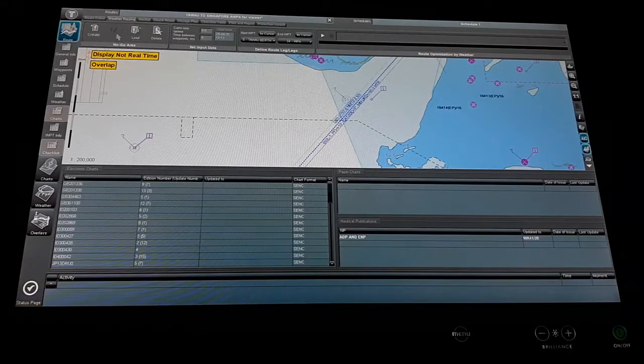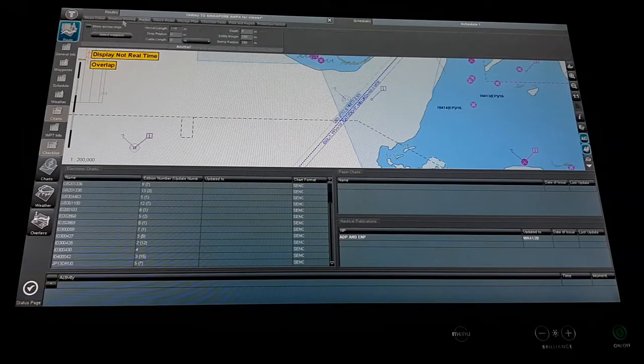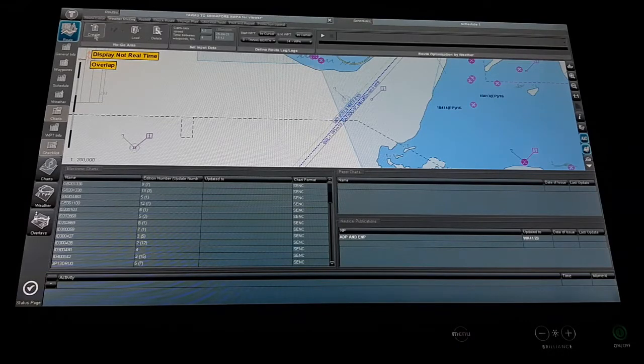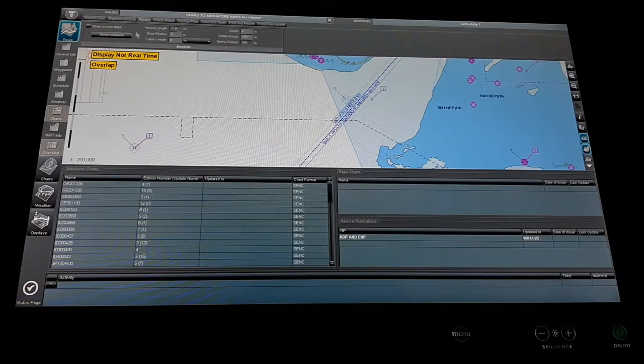After that, we go to weather routing, and the weather routing has so many information. Just go one by one. It's not very important, well, also important, but we normally take weather information directly from the SATC, from the NAVTEX, from the weather facsimile, and also from different websites, and also from different ADP and ENP we are using, so normally we don't rely on ECDIS blindly for the weather information. Maybe we can put some limit, so this ECDIS can give an alarm for wind speed limit. If it crosses that limit, maybe any typhoon warning or something like that, at that time you can put all this value over here.